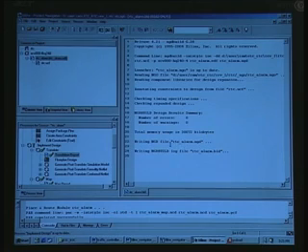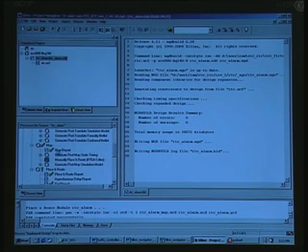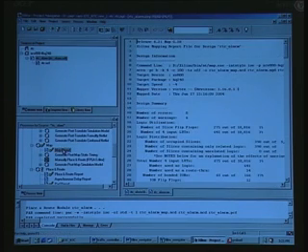This is for the next project that you are going to take up. This is a real time clock. RTC_alarm is the design file, and if you want further details, mapping report, you can just go to map here and then double click on map report, and out comes this. Here we have already read these points, and it reports number of slices, and for example this RTC requires just 275 slices of flip flops out of 18,000 on the device.